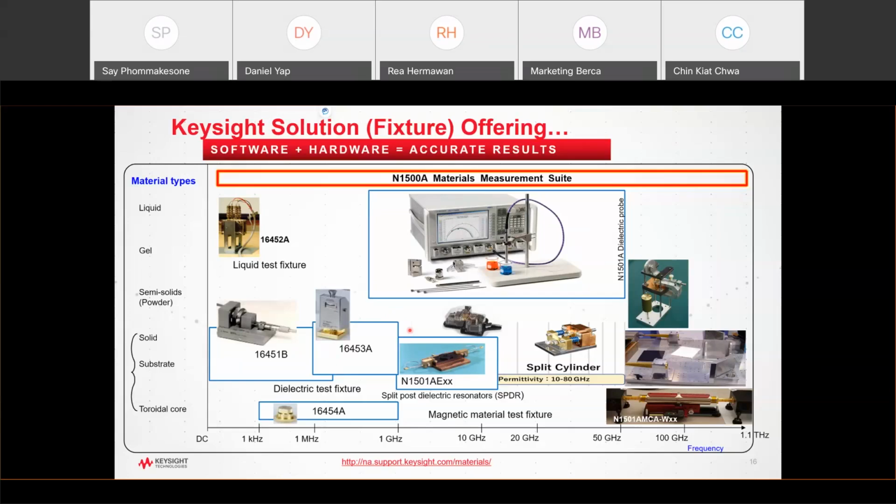If you can fit your sample inside a waveguide, and if your thickness is equal to a quarter wavelength or half wavelength, then definitely you can use a waveguide. If your sample cannot fit inside the two waveguides, then you put the sample in between two waveguides and tie them together, like a sandwich, but your sample is actually not inside the waveguide.